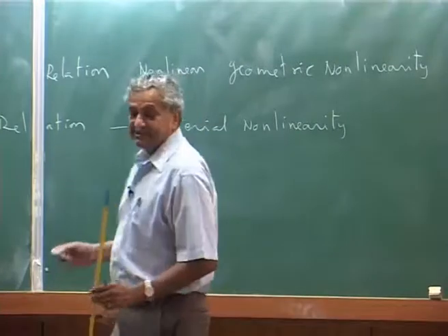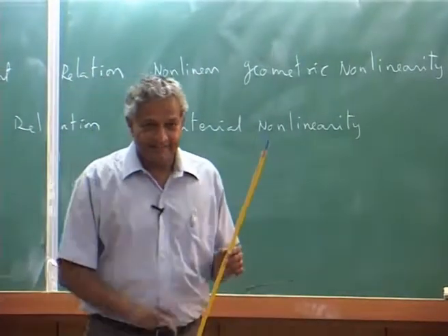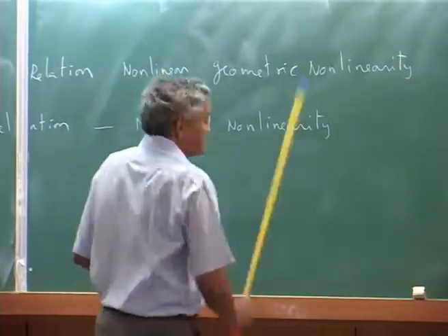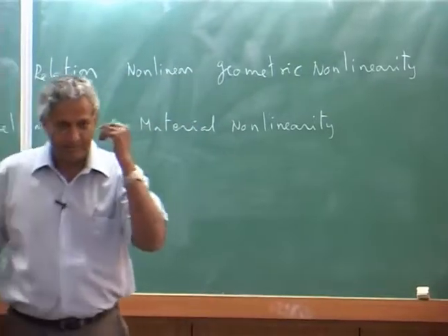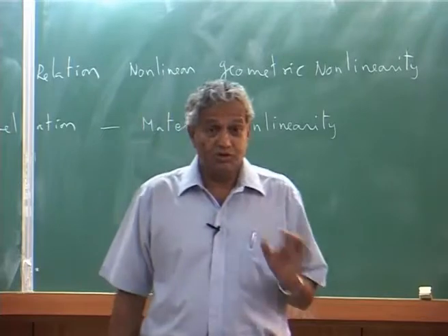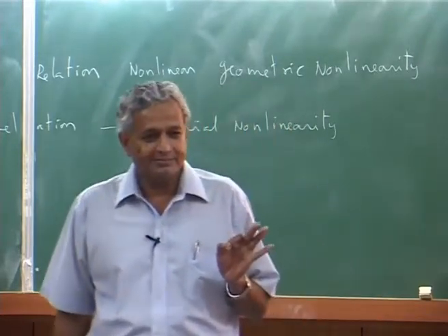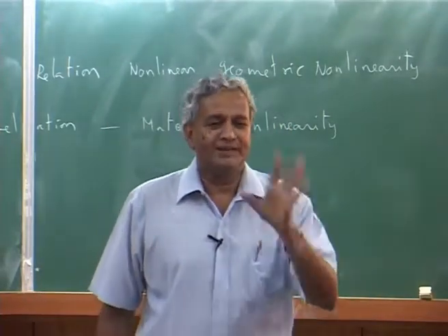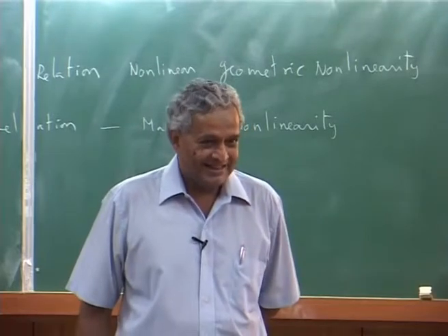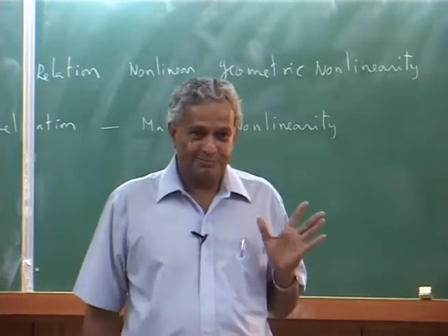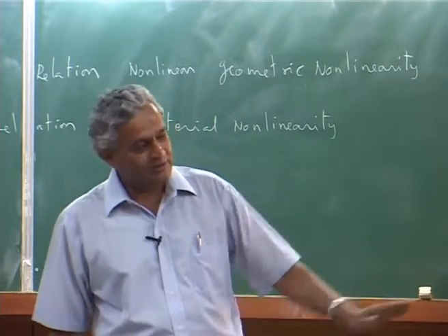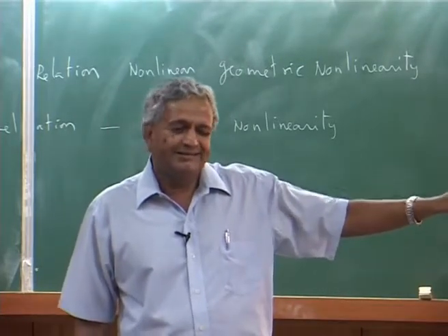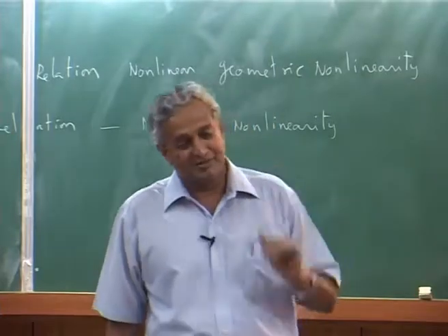These are the basic things, but we do not go to material nonlinearity. The key is whenever you design a blade, you make sure that the strains are small, actually infinitesimal strain. Strain is small, but the strain to displacement is not small, because the displacements are, they do not say large, they say moderate deformation.